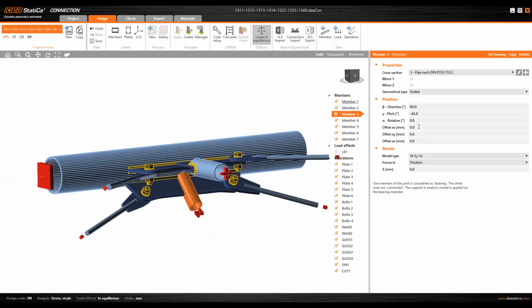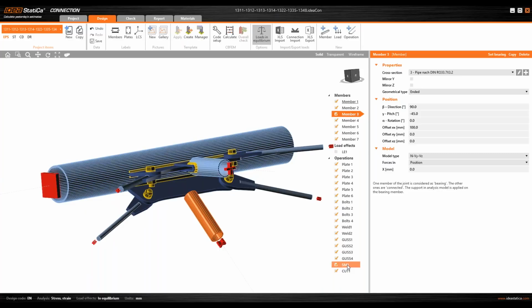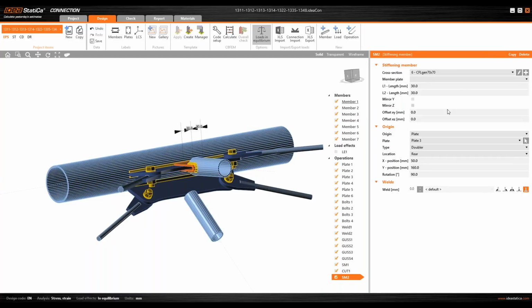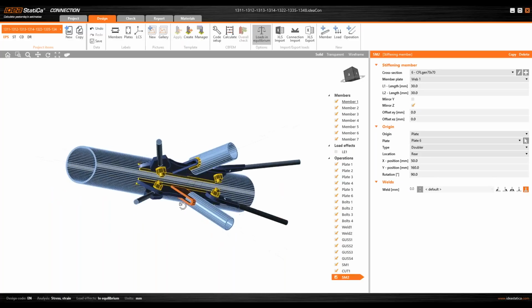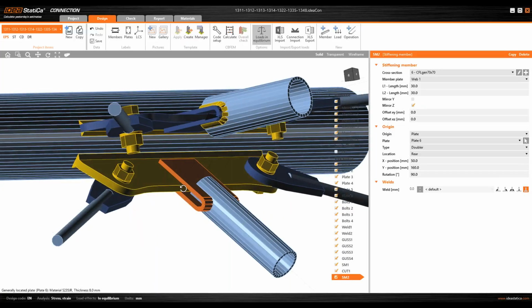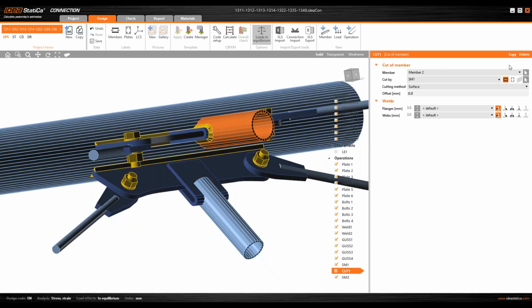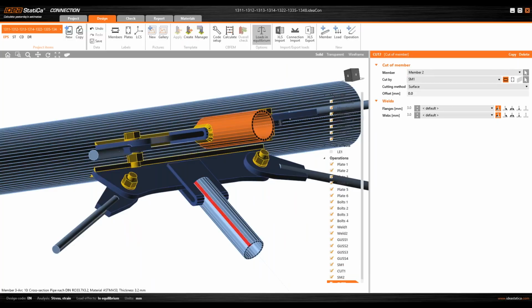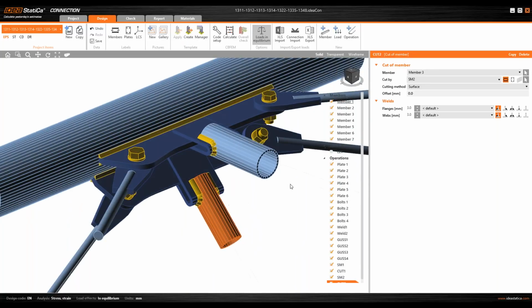Now, of course, I will copy these 3 operations for the lower tube as well. So I will first shift it by this 100 millimeters as well. And now copy the clip like this. Here, whoops, this is okay. I will just mirror this clip by the Z-axis to rotate it and copy the cutting operation. Good.